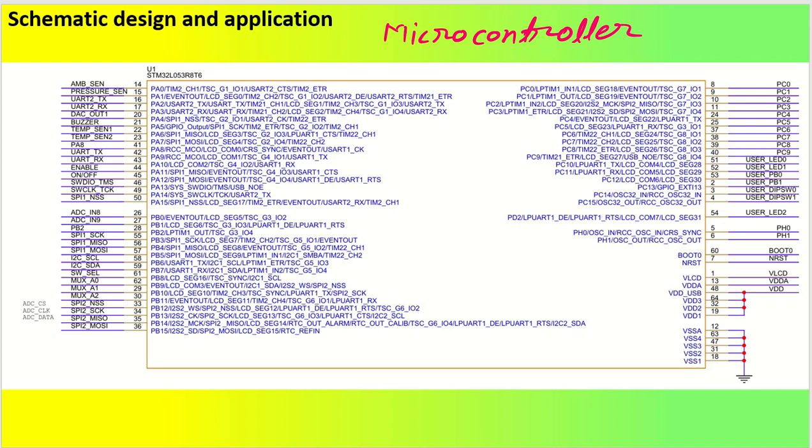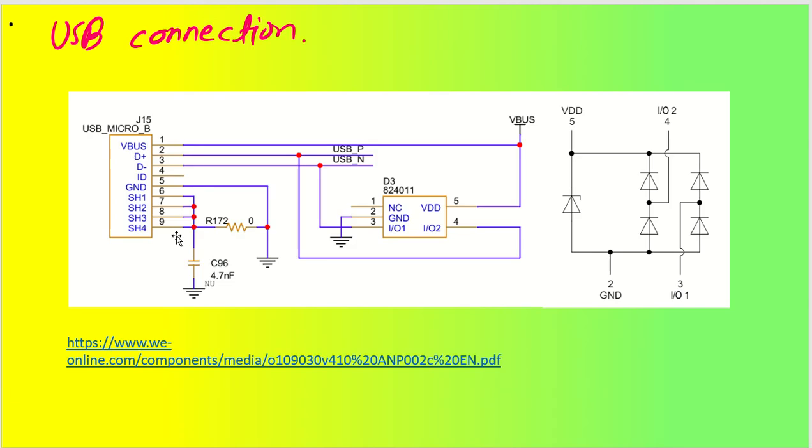As you can see, we have already connected UART2 TX and UART2 RX, and I have taken one more UART pair. We'll utilize these two UARTs for our different applications: RS232, RS485, and UART to USB. Let us see the first one.